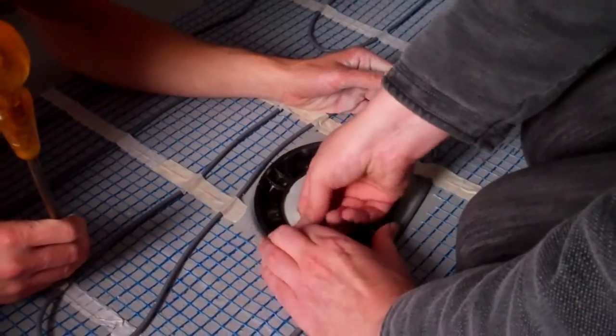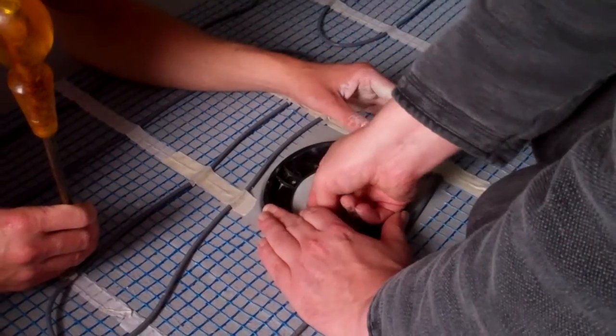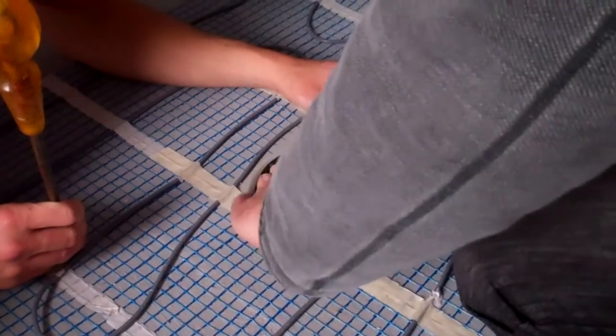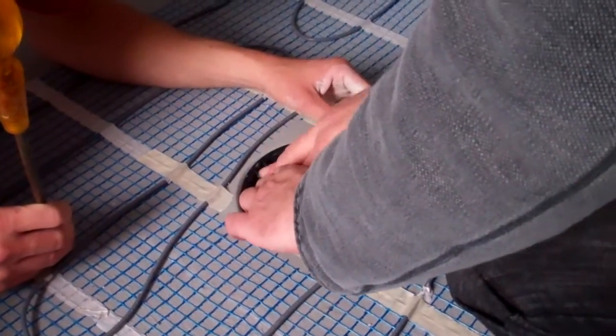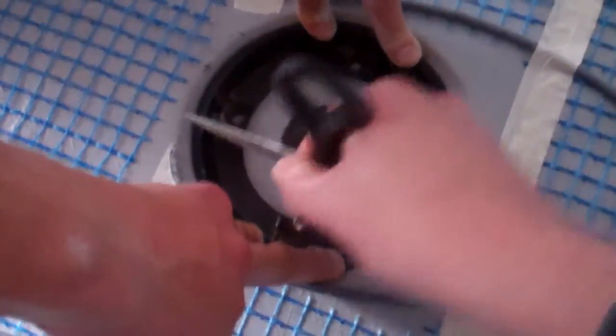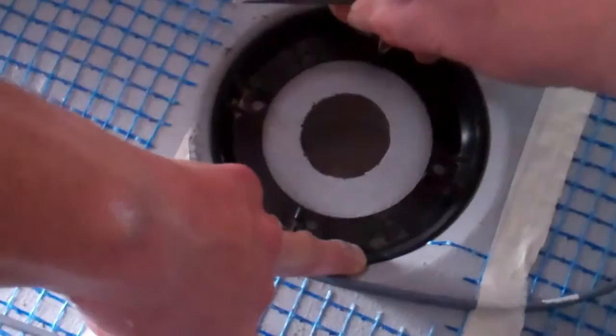In this wet room, Eberco underfloor heating mat has been installed. This can be bonded directly to the aquaproof or installed within a screed prior to tanking. Before tiling, we have to install the clamping ring into the waste. The 4 screw holes in the clamping ring need to align with the 4 larger threaded holes in the waste body. Firmly push the clamping ring into position, stretching the sleeve into the waste.